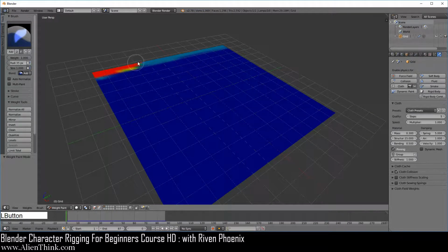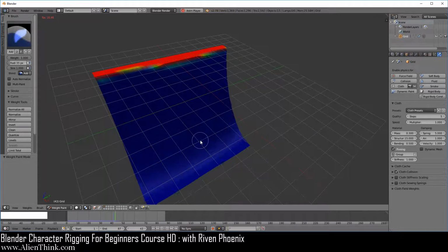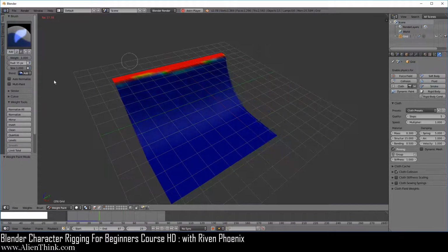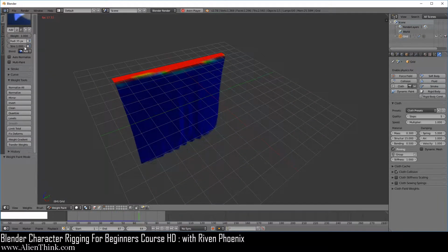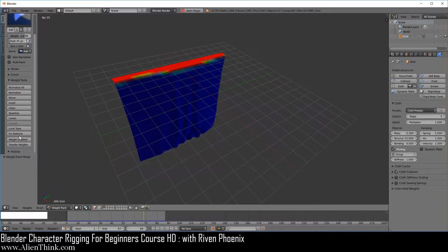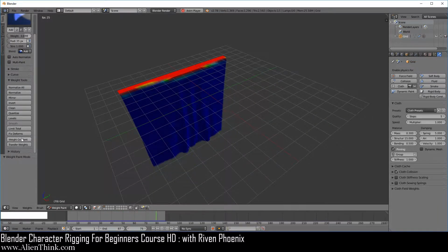Go ahead and add a much higher value. Go ahead and click on play. Now you'll notice that it's going to pin like this, okay? So it's just a piece of cloth that we're simulating. So now what we want to do is actually use this concept. I'm just going to decrease this and look at weight gradient. You can actually have the simulation running if you want, it doesn't matter over here.